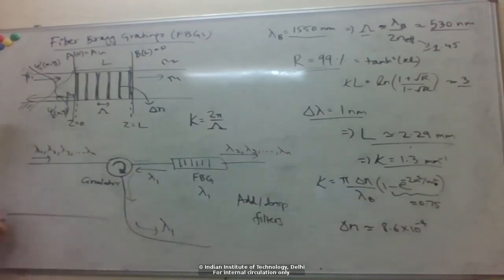So for example, let's say you take a piece of fiber, right? In the middle, you dope it with erbium. So here you have erbium doped fiber, right? So this is like the gain medium you already studied, right? So in this region, let's say you have some coupler here. It's a 980/1550 coupler, right? So you send your 980 pump.